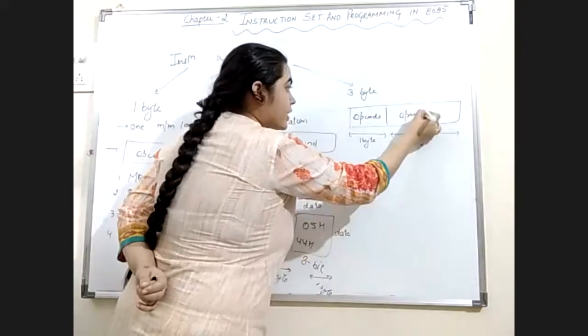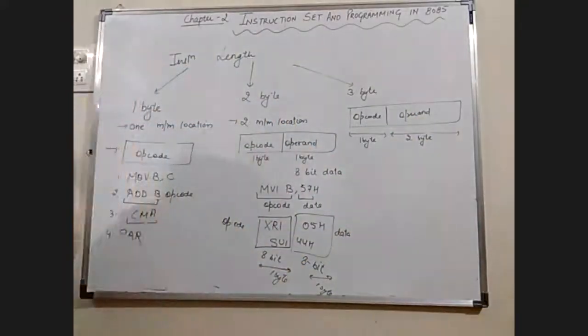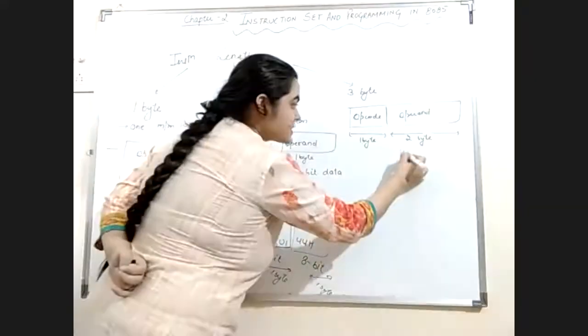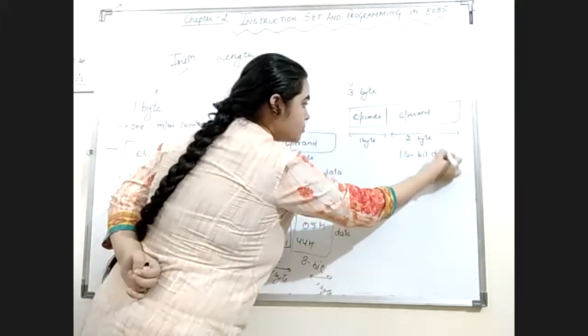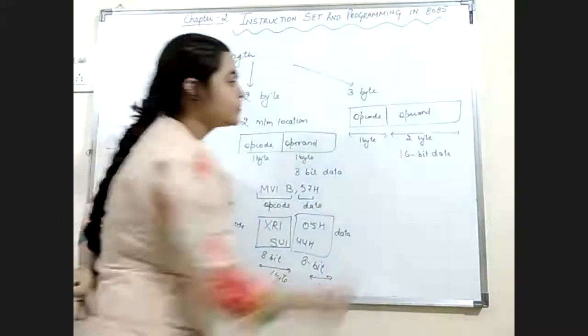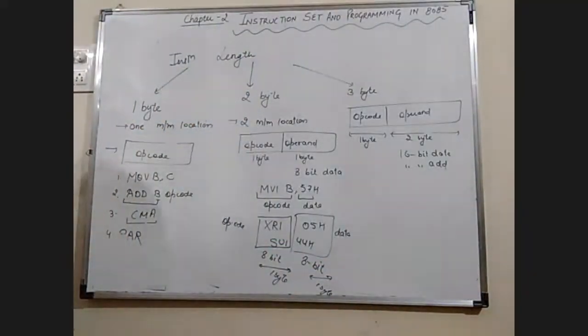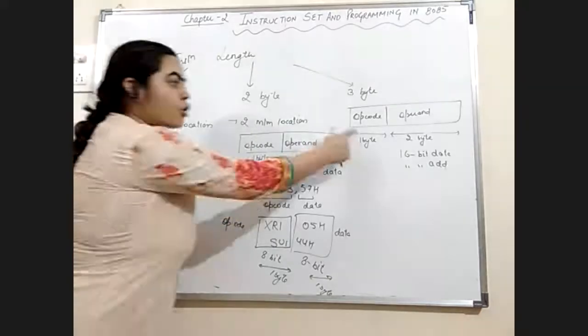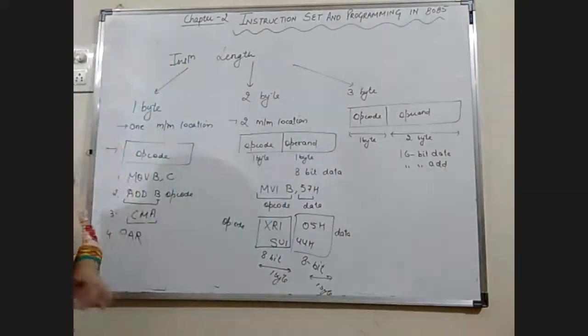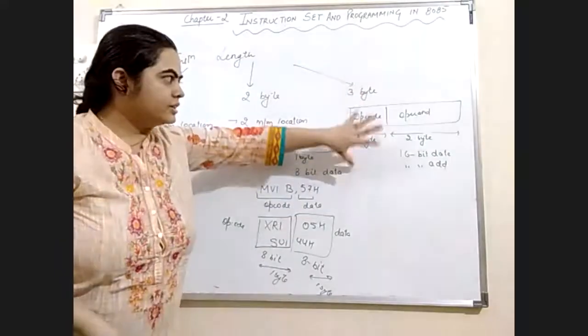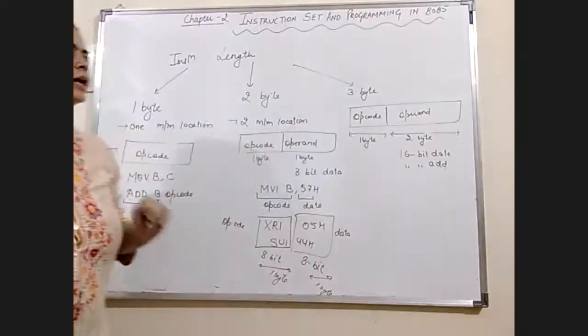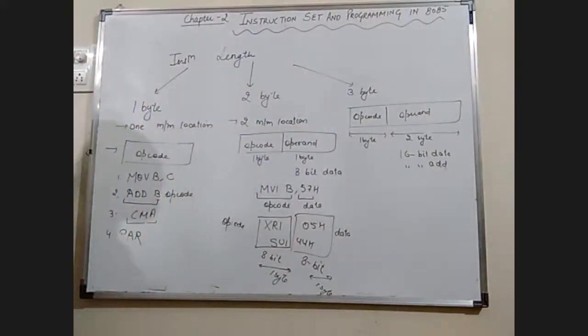Here the operand is always either 16-bit data or a 16-bit address. The 16-bit data or 16-bit address occupies 2 bytes of memory, while the opcode occupies 1 byte of memory. So overall, these types of instructions occupy 3 bytes of memory.